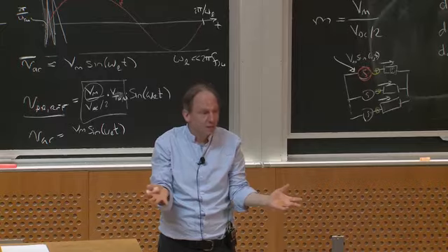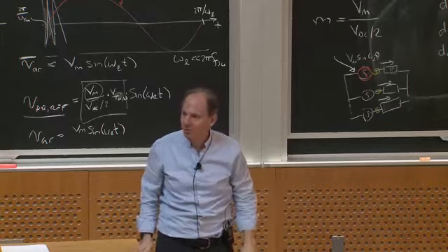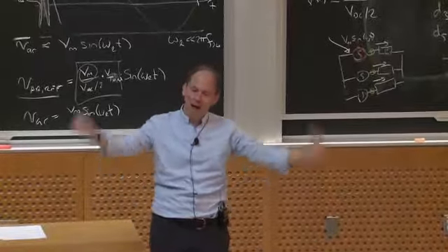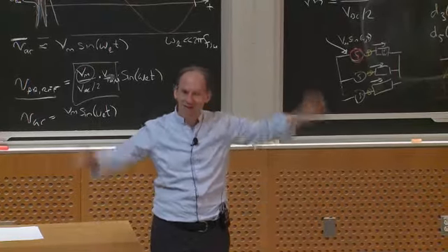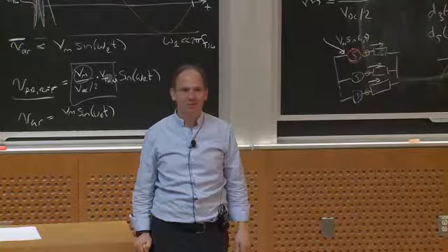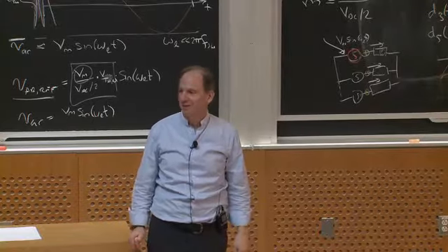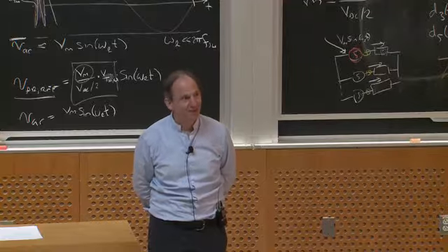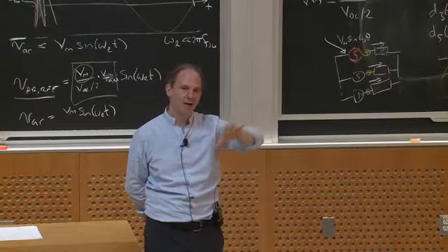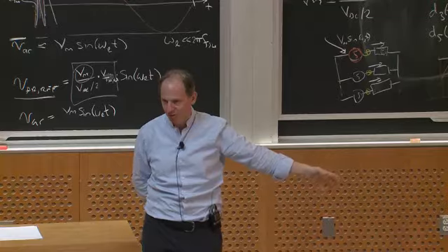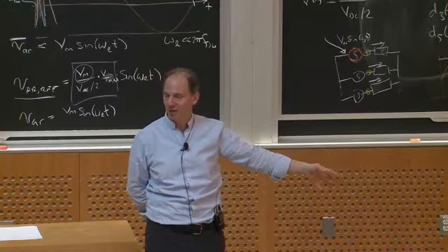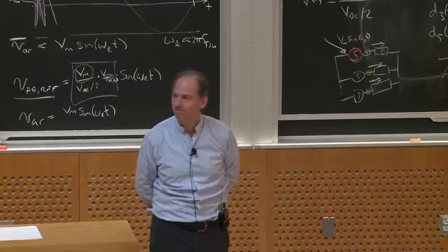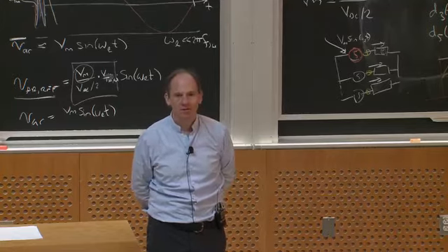In fact, in the Prius, the Toyota guys eventually published a paper saying, yes, we ran out of headroom and we wanted to run our motor faster for higher speed, so we just let it saturate and generate the harmonics, and the motor still worked and we were okay. But you pay a price for that. So people do this, but if you want your waveforms to be pure and not generate low frequency harmonic noise in your load, you have to keep your modulation index down. Any questions?